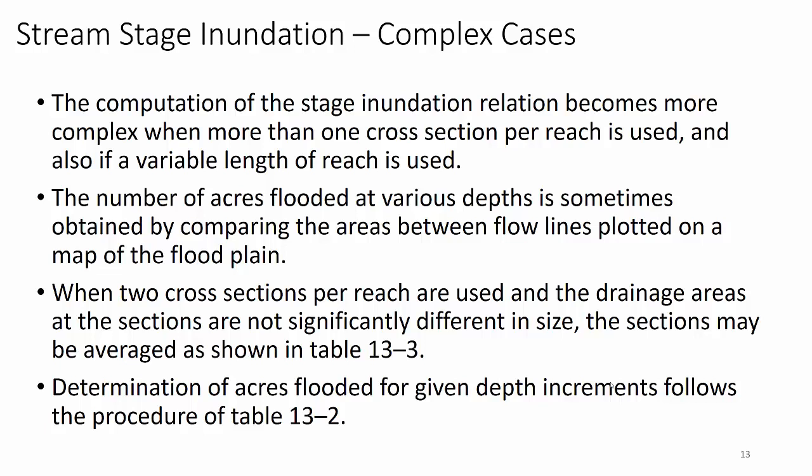Computation of stage inundation relations becomes more complex when more than one cross-section per reach is used. You basically have to average them. So the number of acres flooded at various depths is sometimes obtained by comparing the acres between flow lines plotted on a map in a floodplain. Fortunately, again, we can do this automatically